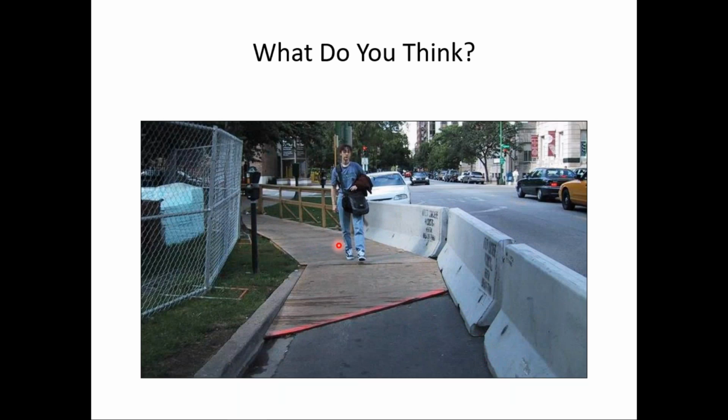And then we have the ramp down to street level. I'm not sure why they didn't just square that off. I don't understand that. And that lip looks like more than a 1/4 inch vertical. Again, looks like they've spray painted it with fluorescent orange paint to attract pedestrians' attention. But again, that's not going to help somebody with an assistive device get over that lip. So a better transition there would have been appropriate.